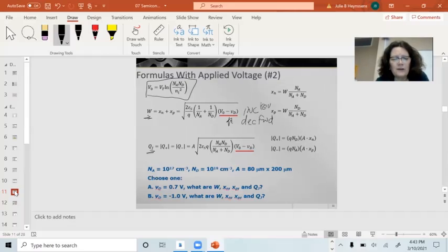The part that changes on the charge in the junction is this part again. Instead of having just V0 there, we have V0 minus the forward voltage on the diode. And the textbook may have it written in some places like that, and in some places like this, and you may see those if you check on the internet too. It's the same equation. You should see the saturation current.